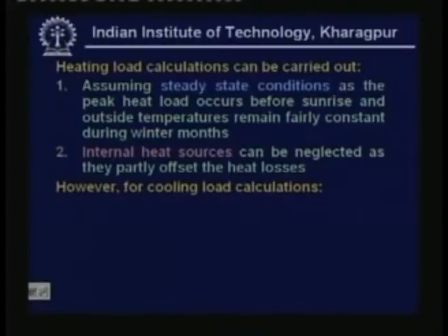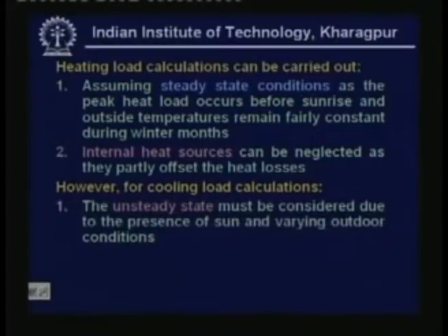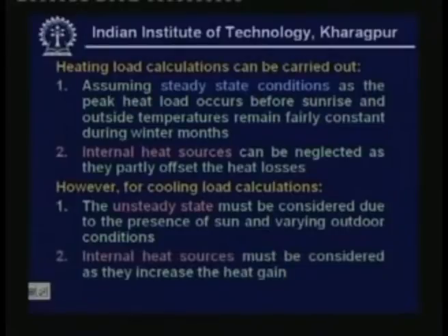However, for cooling load calculations you must consider the unsteady state because of the presence of sun and varying outdoor conditions, and we also have to consider the internal heat sources as they increase the heat gain. As a result, you find that the cooling load calculations are invariably more complicated than heating load calculations. So in this lecture I shall first discuss in detail the cooling load calculations, and the procedure for heating load calculations is almost similar and it is much simpler than this.